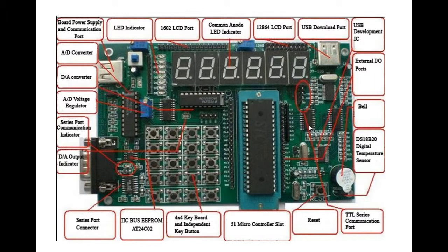In lesson 1, when we introduce the LED diode application, and in lesson 6, when we introduce the analog to digital conversion test, I will show you how we can apply those 3 latches. This one is an oscillator. This oscillator is 12 megahertz. It is used for the communication purpose, or used for this port.